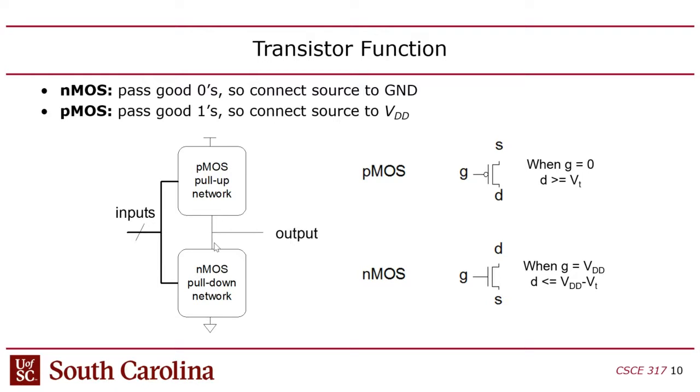The problem is that when the transistor turns on, the bottom plate of the capacitor is no longer the body of the transistor. It's actually the average voltage of the source and drain, because you've got the channel. Once that channel is established, you basically don't really have a bulk anymore. You decouple the channel away from the bulk, the body of the transistor, the substrate.